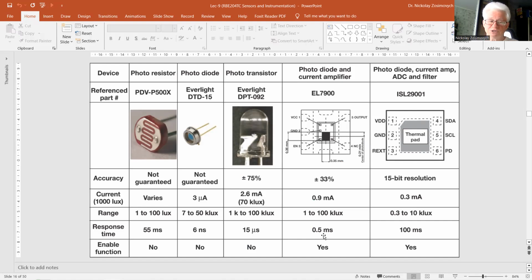Pixel size of both line and area scan cameras is in the order of 5 to 15 micrometers. Current research aims to increase the resolution, number of pixels, and the speed. Usually it's measured in either pixel acquisition time or frame rate.